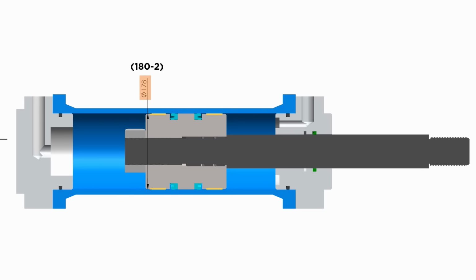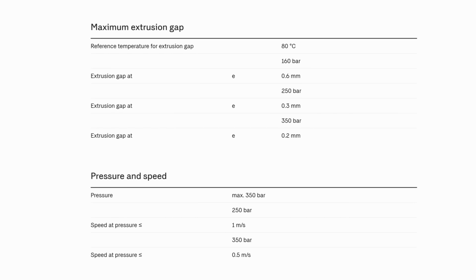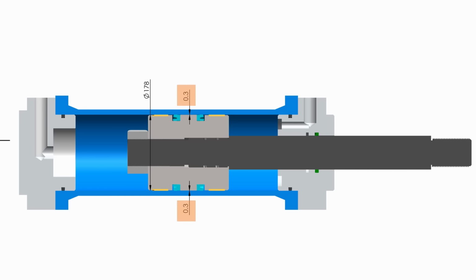And in the middle step, I have maintained an E gap of 0.6 mm, as our working pressure is less than 160 bar, 0.3 mm on each side. Therefore, the step diameter would be 179.4 mm, 180 minus 0.6 mm. So this is the minimum size, or LMC, least material condition size, and we will maintain this size in the manufacturing drawing, considering it as a bore diameter tolerance.